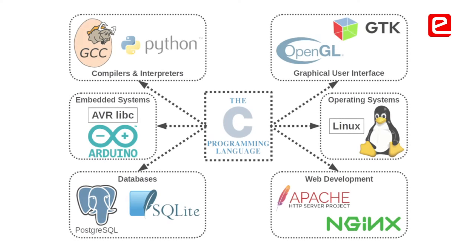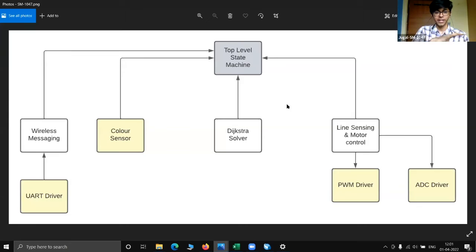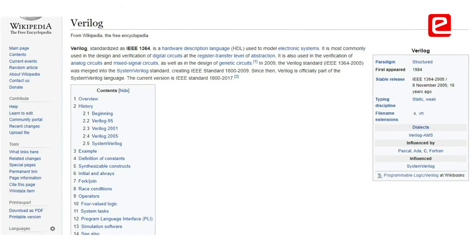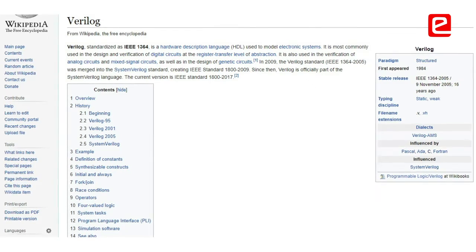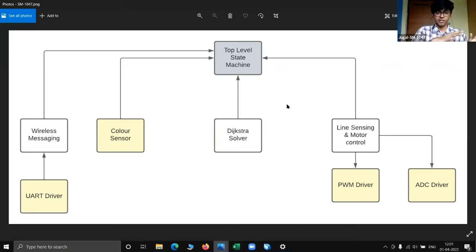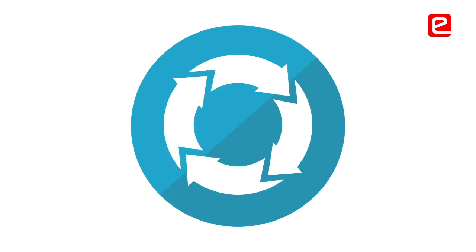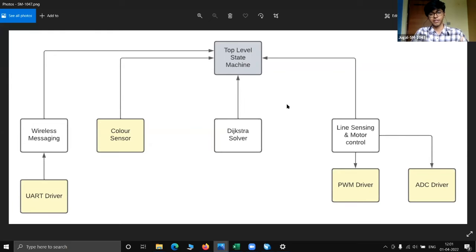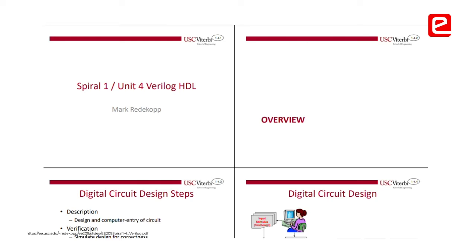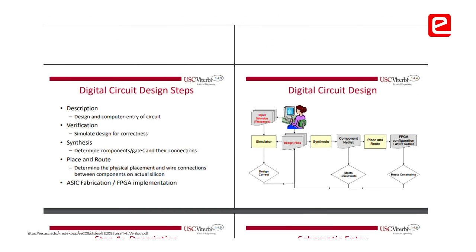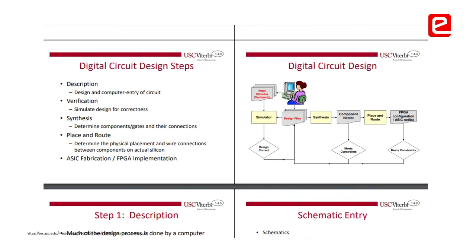Everyone has experience in C and Python. So relating to that experience, they try to fit it into Verilog, and they expect the same behavior from Verilog. So they end up choosing Verilog implementations that mimic the C-based implementations, like using iterations. So the first thing is to unlearn the previous things that you've learned, and actually understand how synthesis is done and how Verilog is translated into an actual digital circuit.